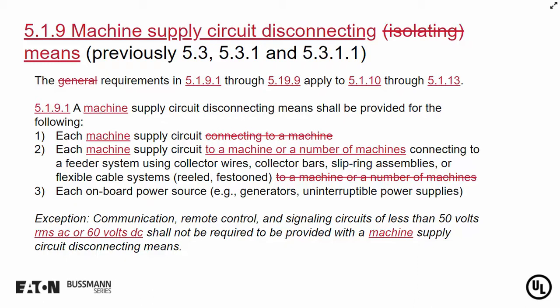So there's a disconnect there, and the question is, should 79 harmonize with 70E? And then also we've got NFPA 70, the code, to be brought into the mix as well. So the NEC Correlating Committee has appointed a task group to look at this and to try to see how to bring the 3 documents together. That's 79, 70E, and the NEC with regards to what constitutes a shock hazard in both AC and DC.